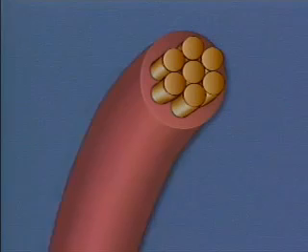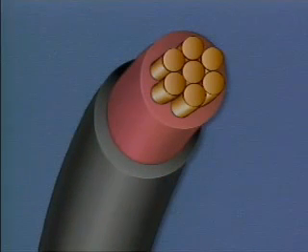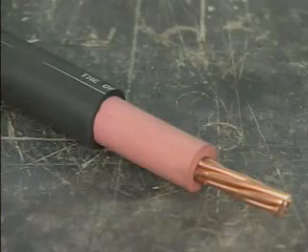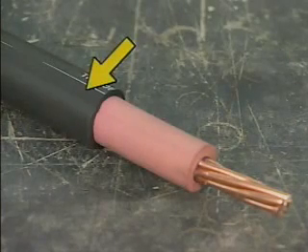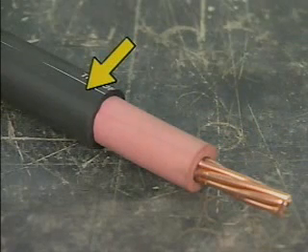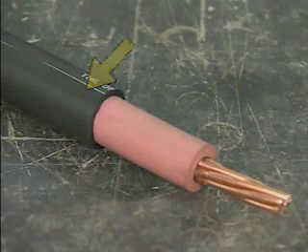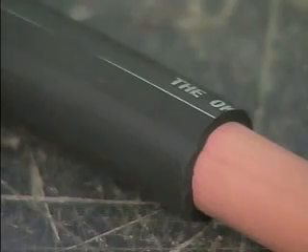Some insulated conductors have an outer layer called a jacket. A jacket provides additional mechanical protection for the conductor and its insulation. Jackets, which are frequently made of hard plastic, are common on conductors that must be pulled through conduit. The jacket protects the wire and the insulation from mechanical damage that could be caused by sharp edges on the conduit.